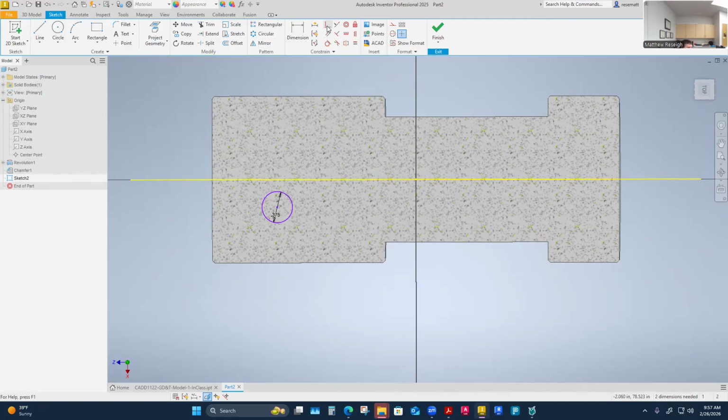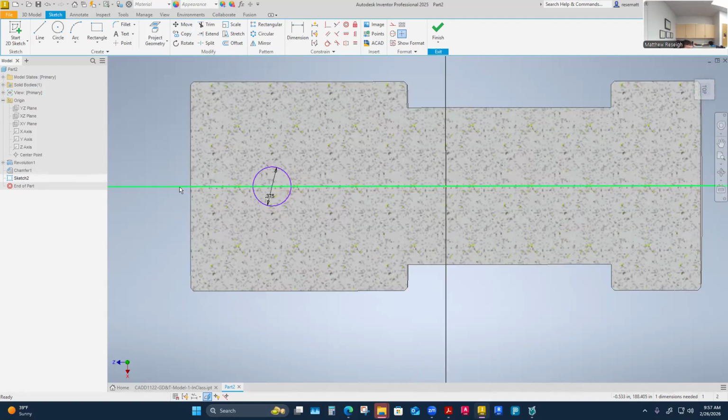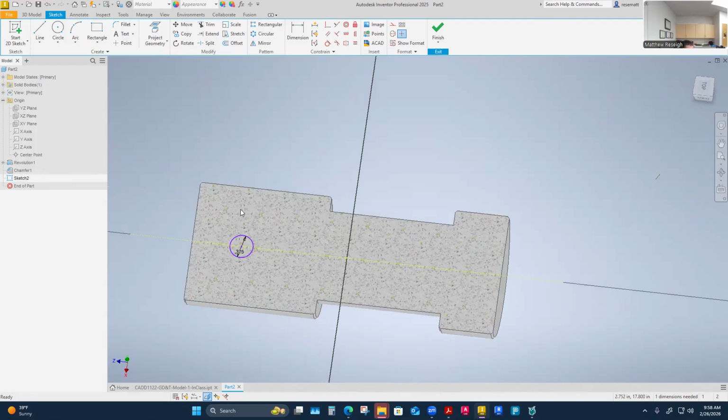And then I'm just going to coincident constrain the center of that to that axis. Usually I turn these to, this isn't going to come, this is going to break. This is what I've said over and over again. I like to turn these to construction lines when it's going to divide my geometry. I'm going to use this as a cut, extrusion cut through, and so I really don't want this line to subdivide my circle, so I can just turn that to construction. Then this will be recognized as the profile, not two semicircles. Small deal, but I just sometimes pay attention to that.